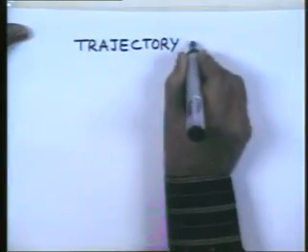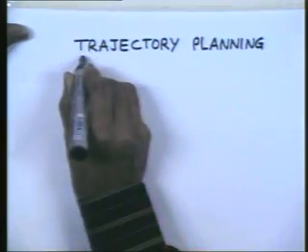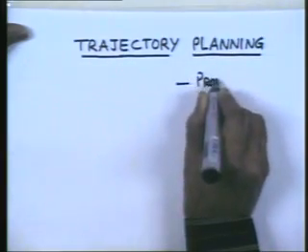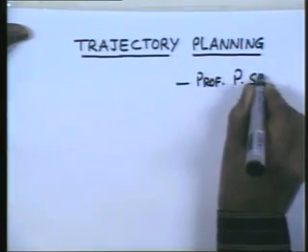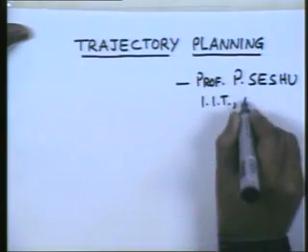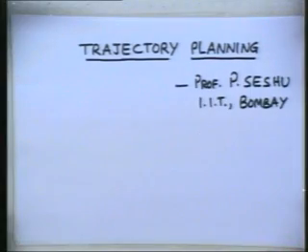And when you look at the trajectory planning, just to recapitulate what we discussed earlier, we talked about the way in which the task specification naturally happens in the world coordinate frame, and the lower level control of the motion of the robot manipulator actually takes place in the joint coordinates, because you have the actuators at the individual joints, you have the sensors at the individual joints, and so the controlled motion could more conveniently be achieved in the joint space.